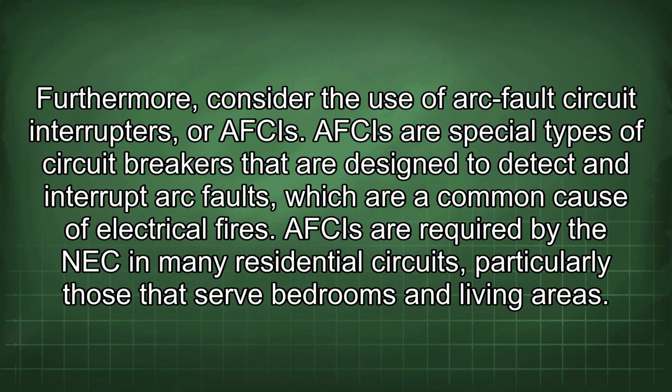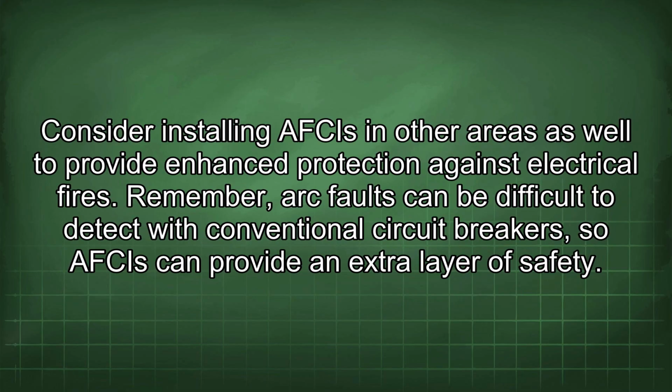Furthermore, consider the use of arc fault circuit interrupters, or AFCIs. AFCIs are special types of circuit breakers that are designed to detect and interrupt arc faults, which are a common cause of electrical fires. AFCIs are required by the NEC in many residential circuits, particularly those that serve bedrooms and living areas. Consider installing AFCIs in other areas as well to provide enhanced protection against electrical fires. Remember, arc faults can be difficult to detect with conventional circuit breakers, so AFCIs can provide an extra layer of